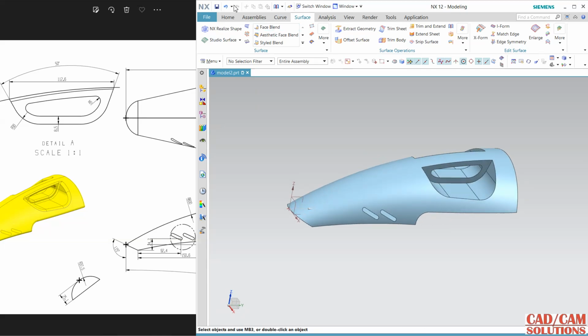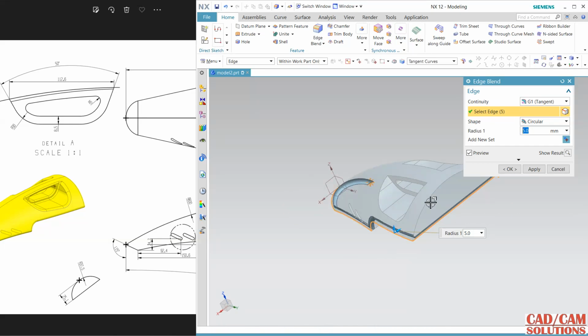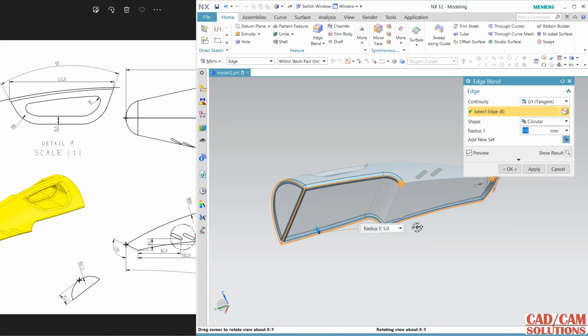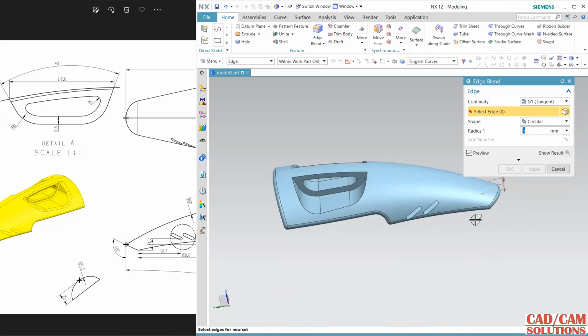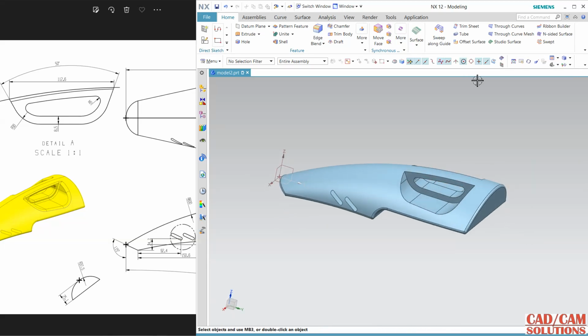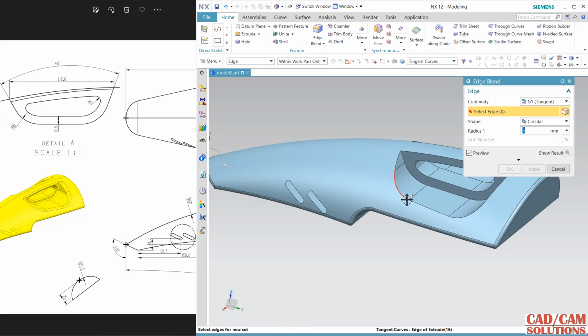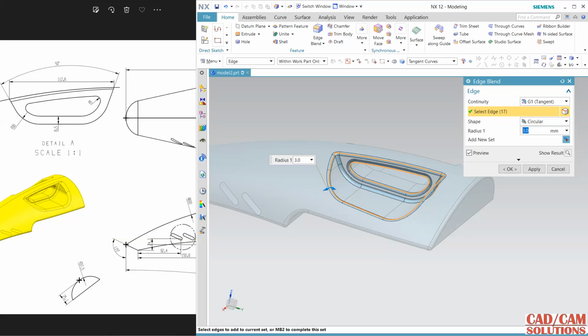Okay, now apply the fillet, and the fillet is 3 radius, it is not given anywhere, so I'm using 3 or 5, sorry, it is 5, right, let's click this, apply, so 5 is not convenient here, so use 3, okay, and again click, select this, this, and this, and the opposite side.